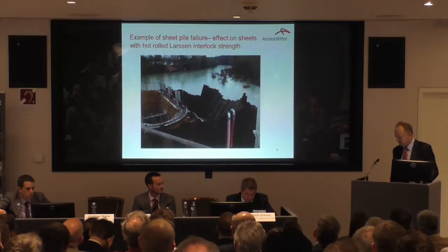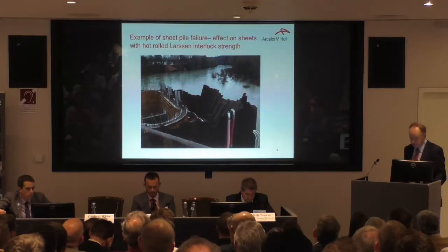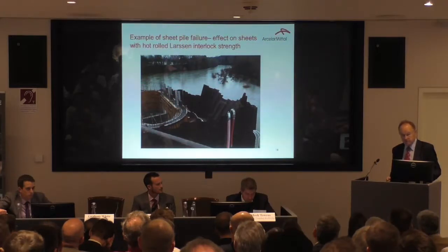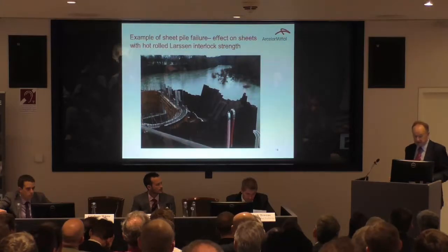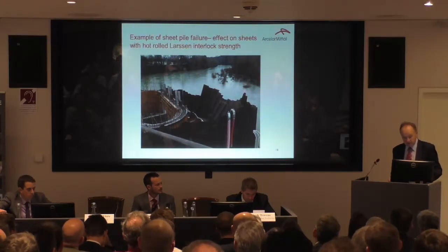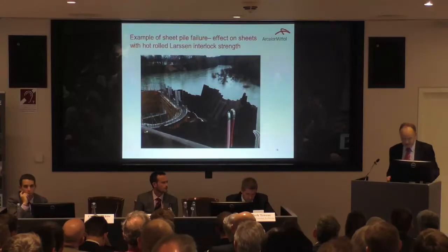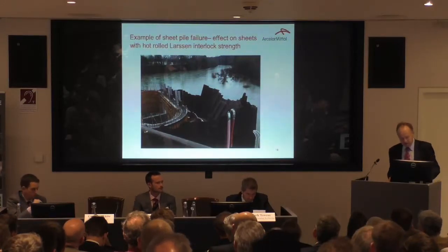We have to be very careful with cantilever sheet pile walls to provide protection because they're very flimsy. But when we have soft alluvial soils that show quite stiff in the bore log report, just the action of a dynamic force or impact can easily loosen them. And in this case, it collapsed on higher flow and removal of passive resistance at the toe. So that's just an illustration of sheets collapsing.